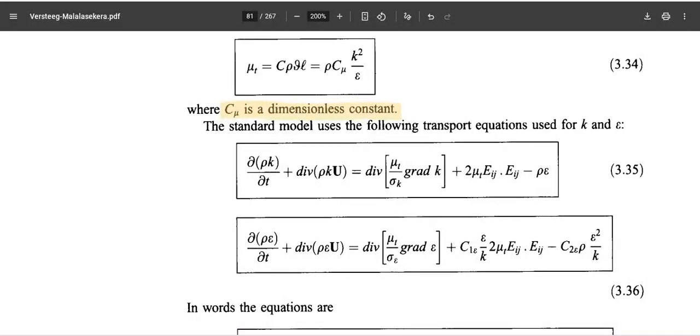In the last video, we saw the turbulent viscosity for closing Reynolds equations, for modeling Reynolds stresses using Newton's law of viscosity based stress-strain relationship, where we introduced a term called turbulent viscosity. And turbulent viscosity, on making a dimensional analysis, can be expressed in terms of k and epsilon, turbulent kinetic energy and the dissipation. These two have separate transport equations called k-epsilon equations, and the model for closing these turbulence Reynolds stresses is termed the k-epsilon model.